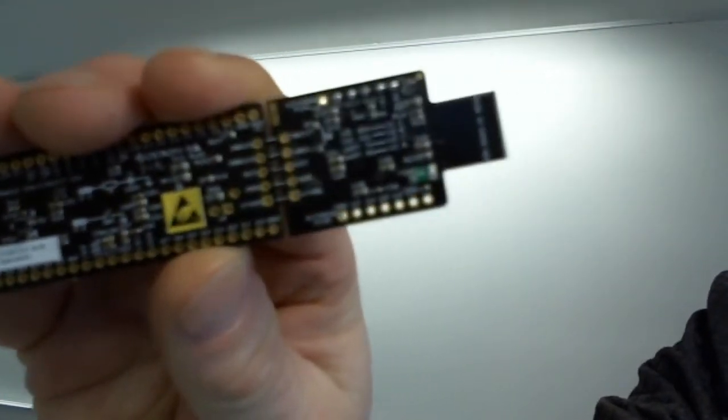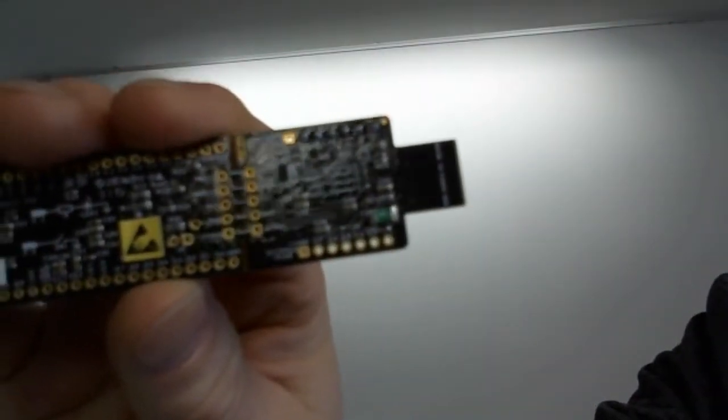All right, it doesn't focus well, but anyways, there's a pin out on the bottom. So UART RX is 12.6, is it 8 or 6? 6, okay. And transmit is 12.7, on the corner pin.